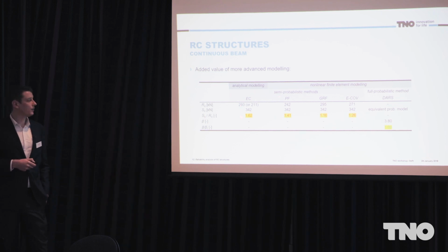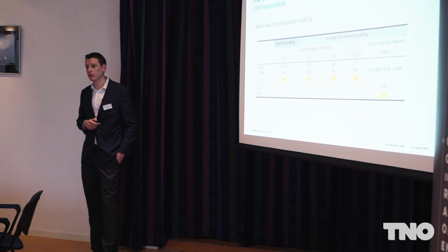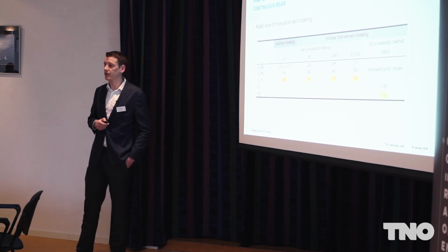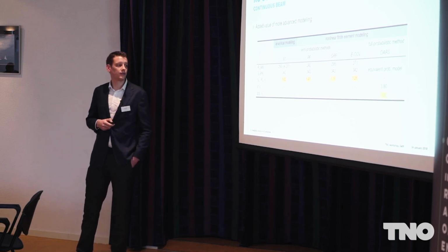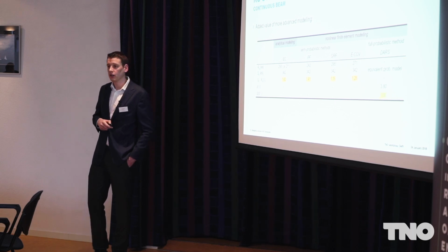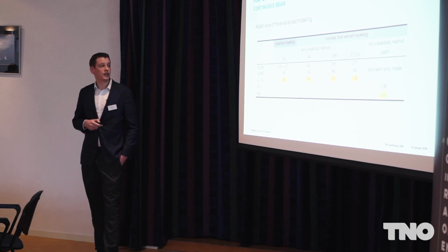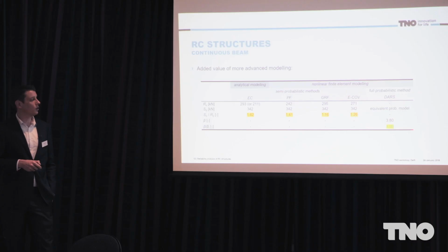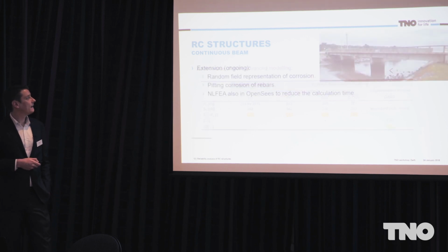So what we see again is that using just an analytical model, just using the static or kinematic theorem of plasticity, if we calculate the resistance of the structure, the structure doesn't comply. And if we move to a more advanced model, taking into account the hardening of the rebar and also a more realistic representation of the material model of concrete, we can uncover some reserves, but these are still not sufficient. So the model is not sufficient, and the structure complies only if we do a reliability analysis.